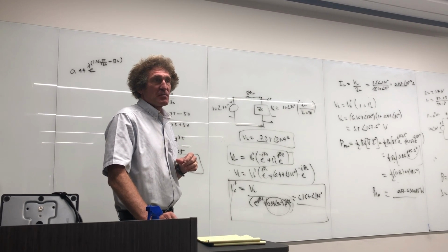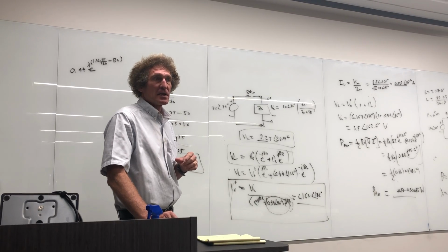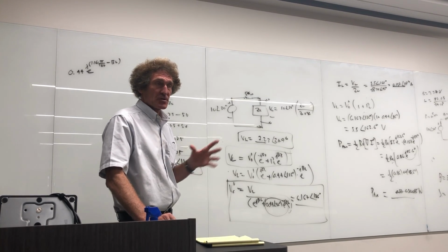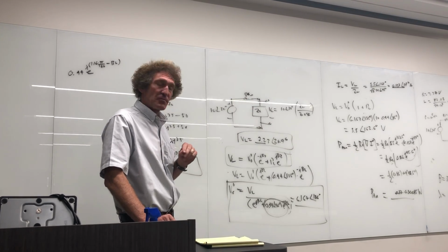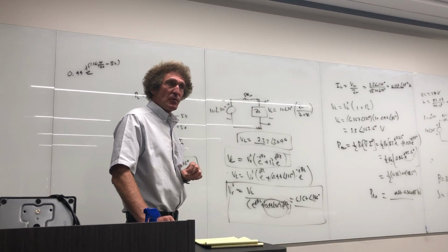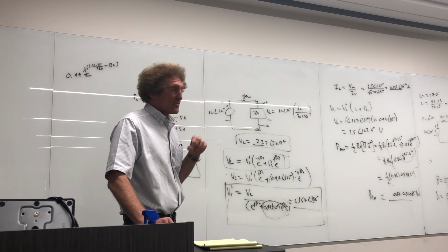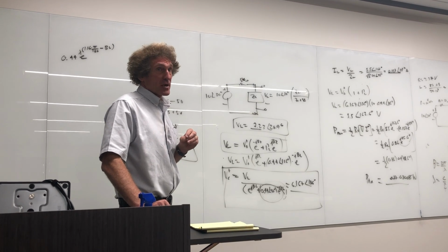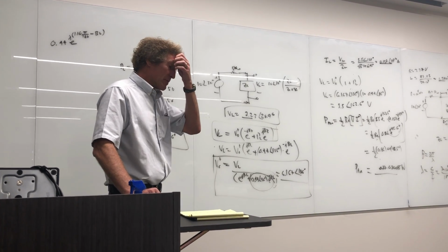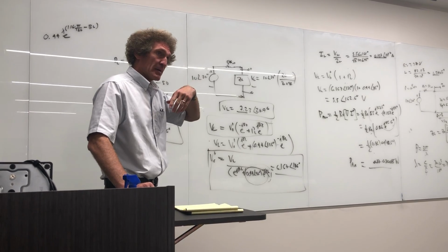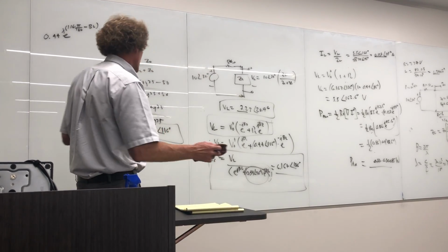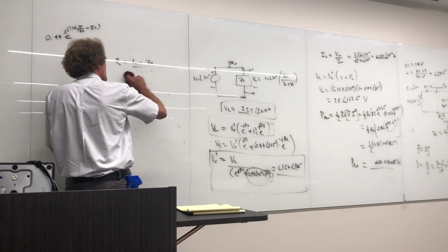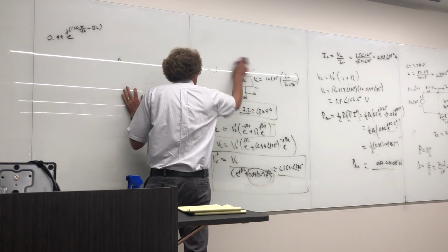A Smith chart is nothing more than a tool used to quickly calculate impedances, admittances, and also doing impedance matching. So if we have a load like this, 25 plus j25, and we have a 50 ohm line, and we don't want any reflections, we can modify that by putting either in series or in parallel with the load another transmission line with a certain termination, and we can get what's called matching, so there's nothing reflected back. And that's the idea. We'd like all the power delivered to the load. And that's what we're going to find out about.